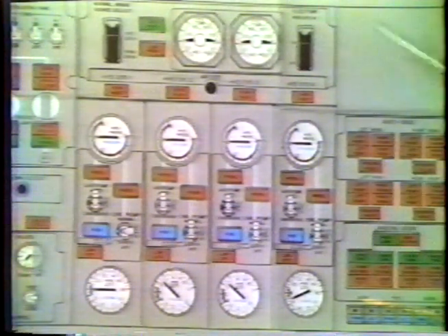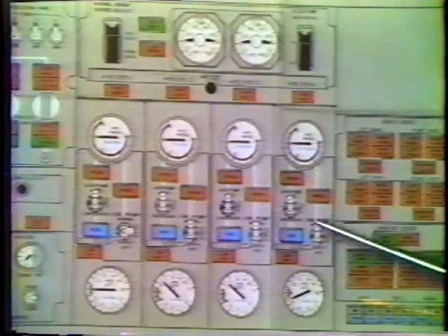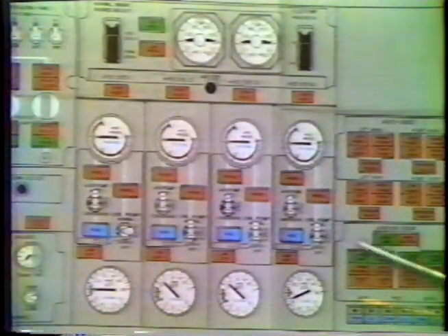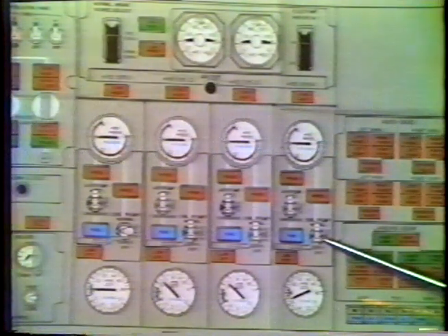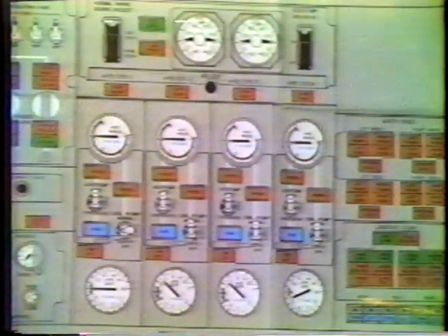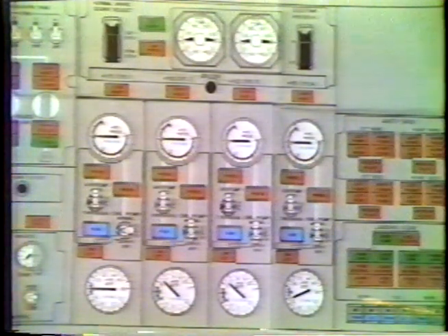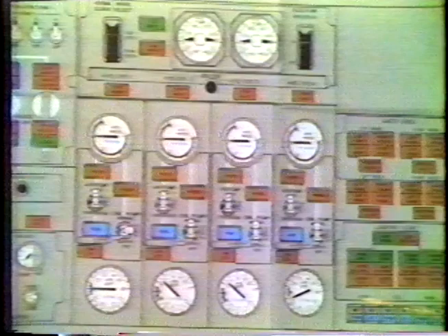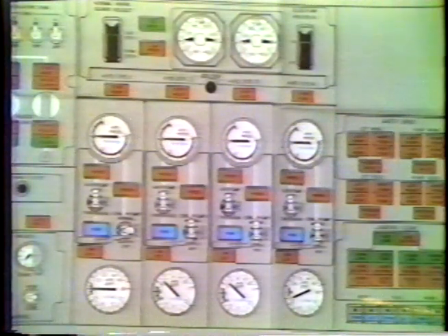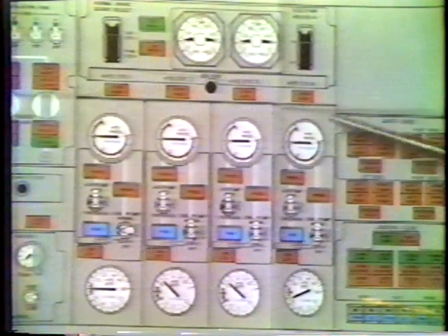Now, if the temperature comes down to normal when the air pump is depressurized and the engine pump is depressurized, then that indicates the problem is in the hydraulic system someplace. Historically, this has been generally due to internal leakage in the flight control actuators, and that would be up to maintenance to find out exactly where it is.